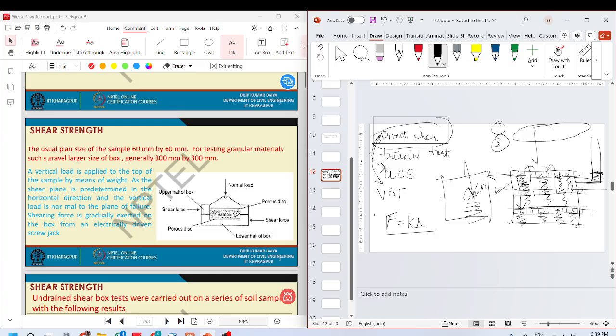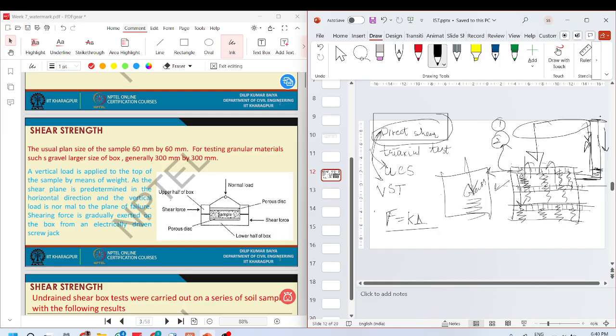And at the instant of the loading, this would have risen up because all the load the water is carrying. This would increase, and then slowly, based on the permeability of these materials, the water would come out and the load would get transferred to the springs, and this level would decrease, and this is what excess pore water pressure is called.